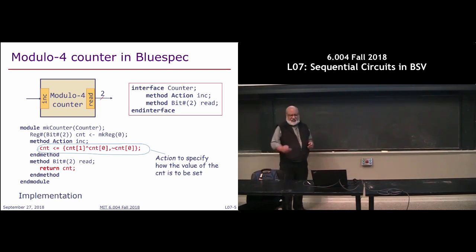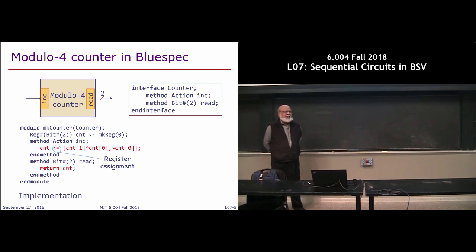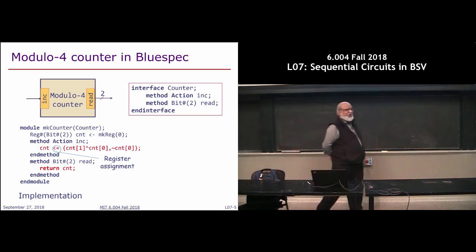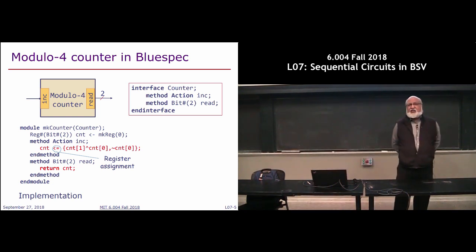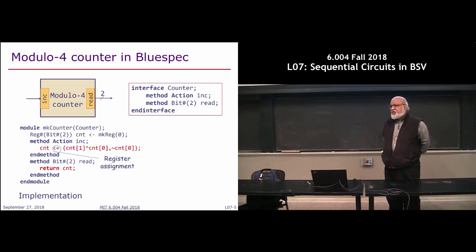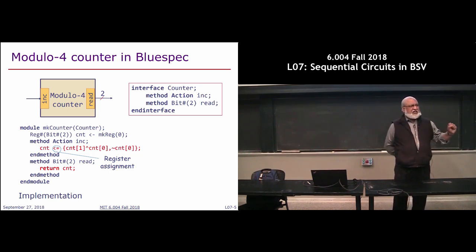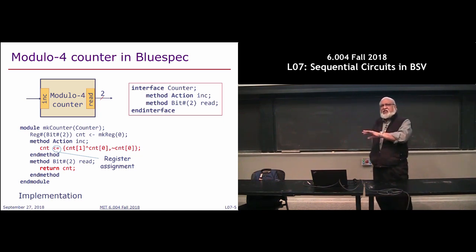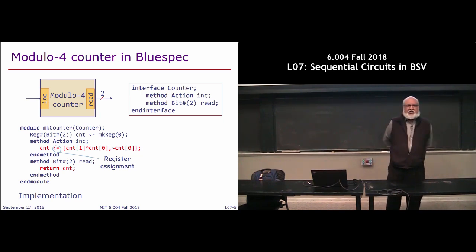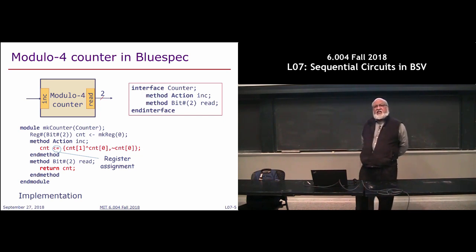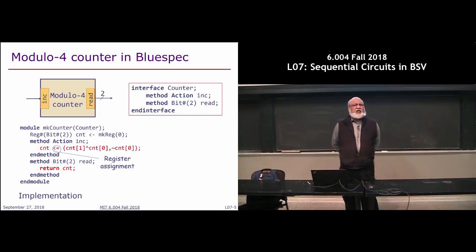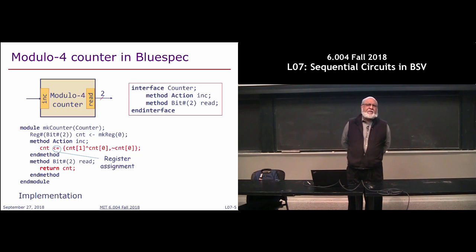To understand the syntax of it, the most important thing is this: a new kind of left arrow has appeared. This is a double arrow which you will use a lot. And this always stands for assignment to a register. So you have something defined, which is a register here, and you're saying there is going to be some value computed on the right hand side, put it in there. Yes? Is the benefit of declaring the interface separate from the module just that you can make different modules that have like the same...